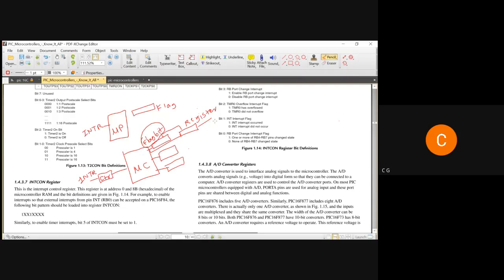Then the register will work, and since this feedback mechanism also provides information to the microcontroller, it will wait for that much time. In this prescaled or postscaled flag, it is 1 to 16. When the event comes, the register is going to notify the microcontroller through some other flag, and the microcontroller will receive that signal. Means the register can communicate to the microcontroller through this channel.